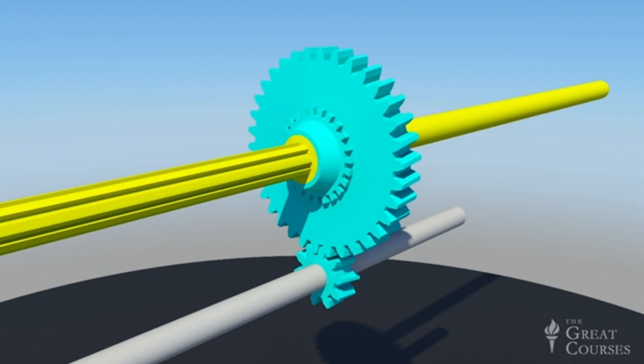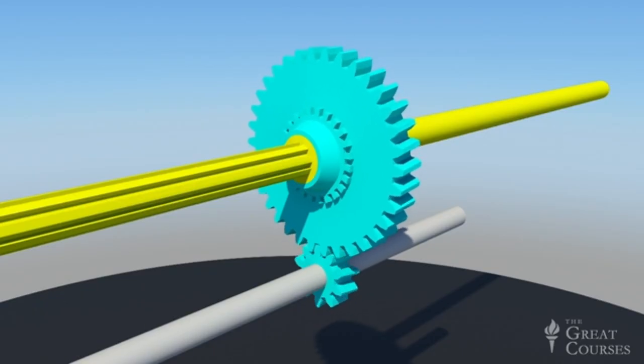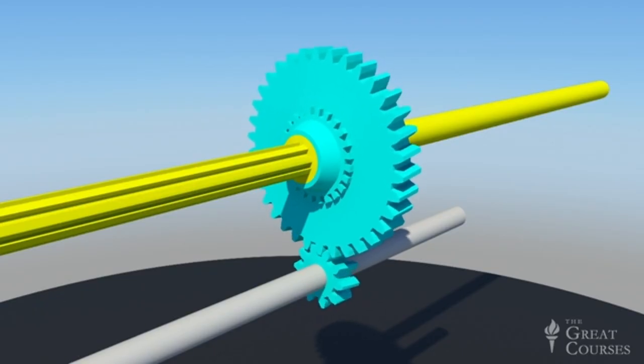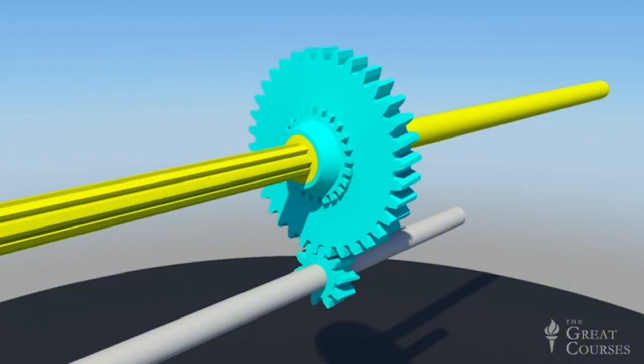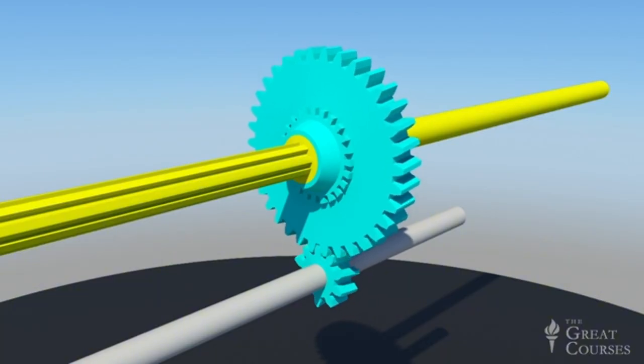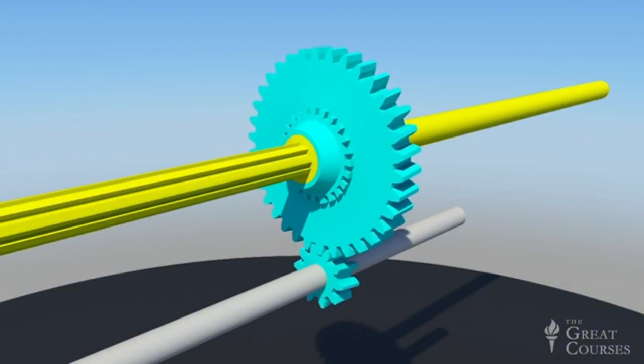In this pairing, the 2 gears always remain meshed, and the smaller gear is permanently fixed to the lay shaft. However, the larger gear is free to spin on a set of bearings inside its hub. Thus, it's free to rotate independently, and it can't be used to transmit power without being externally locked to the